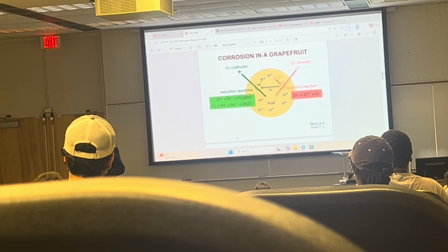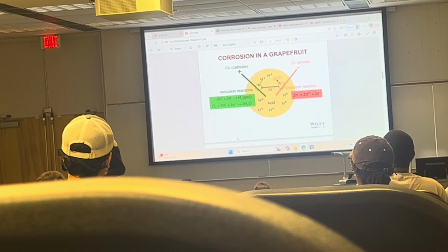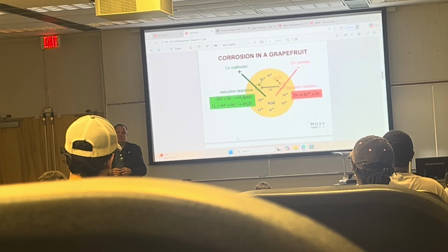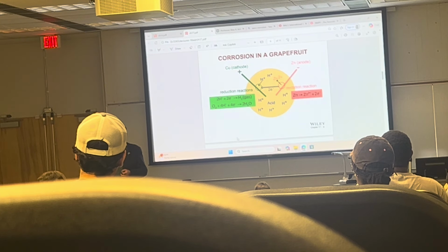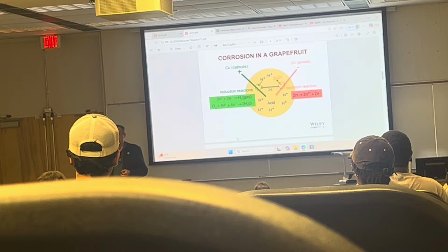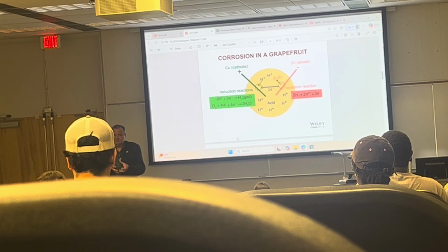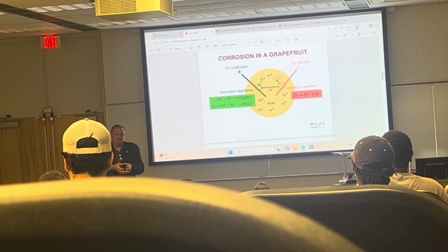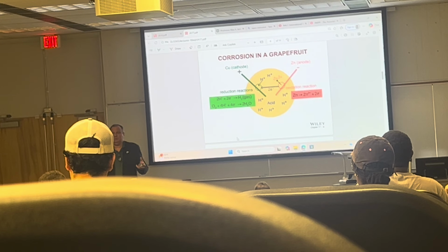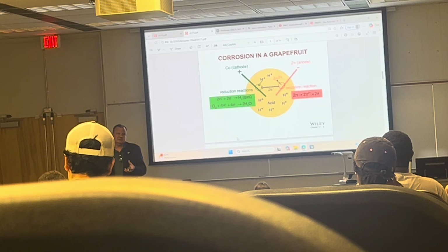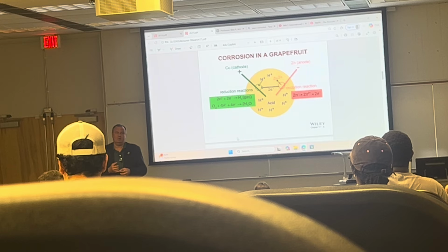But what's the problem with putting it on the top? If you're in Clearwater Beach? Diffusion, right? Salt water can go in and react with metal. And the problem is that rust, which is iron oxide, takes 10 times more volume than the metal itself. So it starts to react, and literally this thing explodes from within. It does not explode, but it expands, and as it expands, the concrete starts to spall.